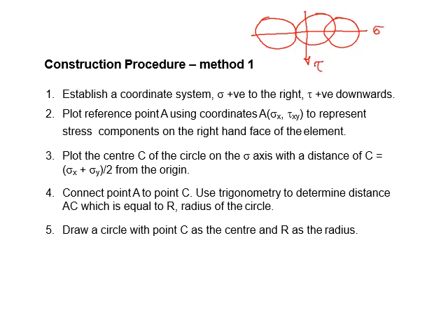The scale that you use for this axis, you have to determine carefully so that you don't get a circle which is too small, that will reduce the accuracy of your reading from the graph, or you don't want the scale to be too large, such that when you start drawing the graph, you find that the graph exceeds your graph paper. Okay, you don't want that to happen. That is the only setback of using Mohr circle on graph paper, right?